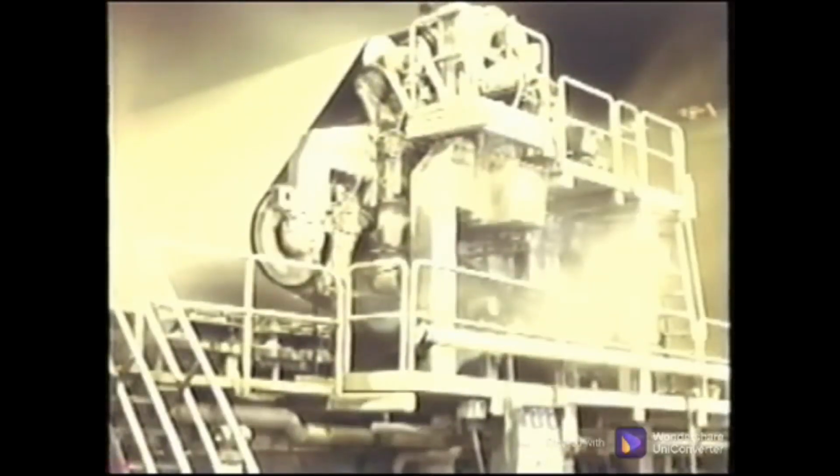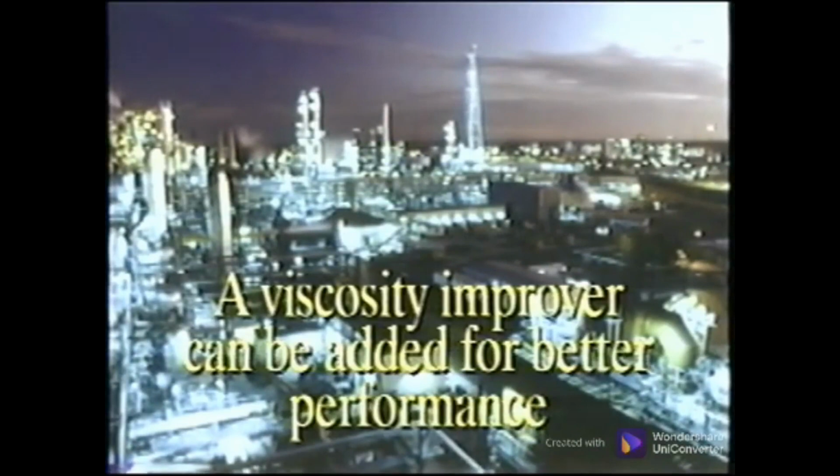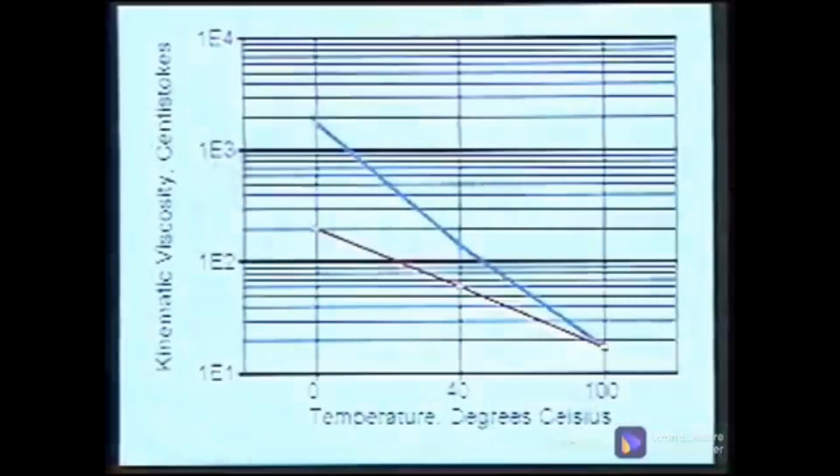High-temperature applications require higher viscosity or heavier oils than colder operating temperatures. Viscosity must be adequate to separate the moving parts at the operating temperature of the machine. When a machine must operate in both cold and warm temperatures, such as outdoor applications, an additive package called a viscosity improver can be added to the oil to make it perform suitably in both environments.